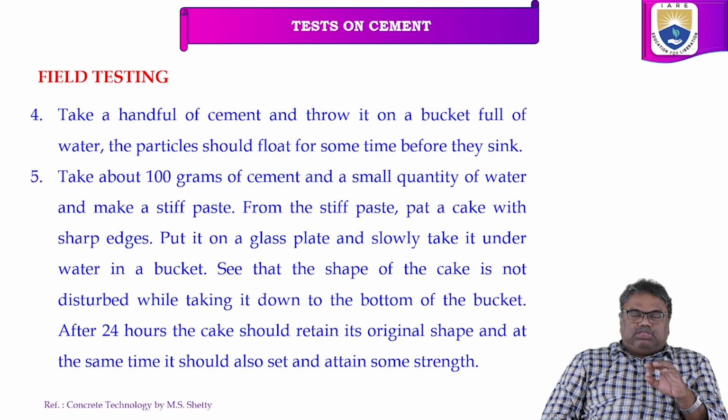So the cement particles should float on the bucket of water, right? Before sinking, they have to float. After that, they will absorb the water and sink. So this is the fourth test we need to do in the field. And the fifth one: take 100 grams of cement.